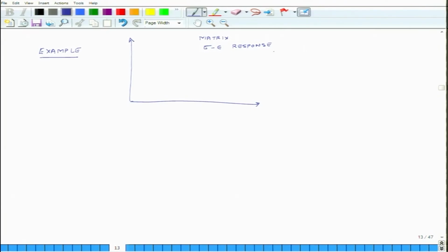So, how do you generate this curve? You take a piece of material which is only matrix, pure matrix, and you apply some force, and you keep on measuring strain and stress in the system and you make a curve out of it. On the x axis we plot strain, and on the y axis we plot stress in the matrix material. And this matrix material behaves something like this.